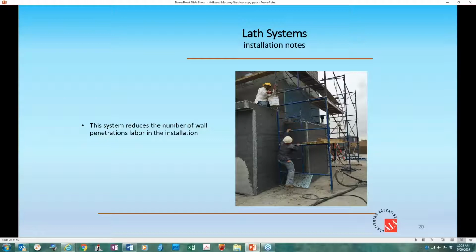When you're using a lath system, paperback lath is typically hot glued to the lath. And unfortunately, in cold weather, wet weather, and hot weather, it can come apart. LathNet is going to be mechanically fastened and can be stored underwater for all it matters. It won't have any effect on it coming apart.